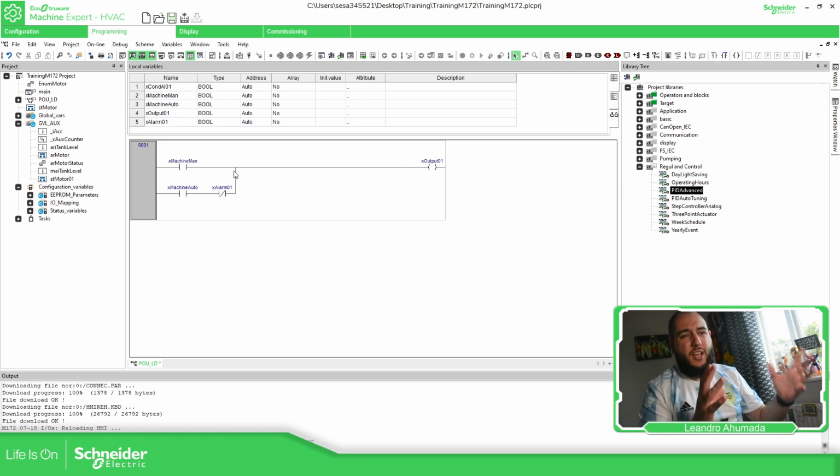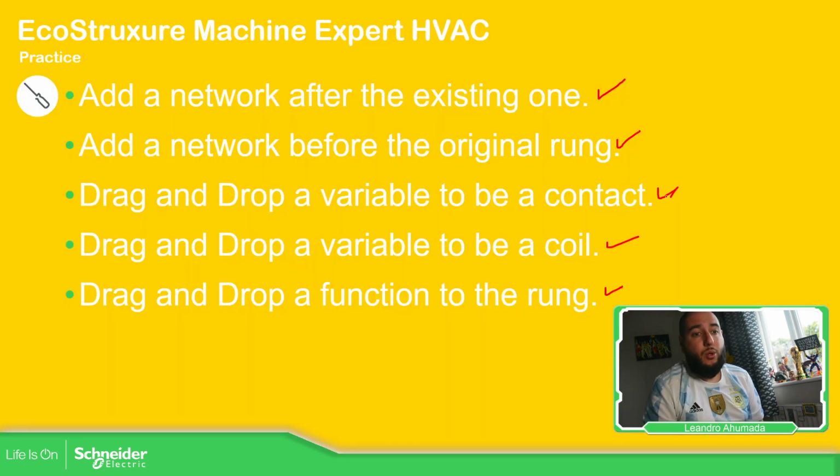So you can easily check, okay, I have the condition that came from the manual, I have the condition that came from the auto, or another one, and then you just see what happened with the output. So the ladder is easy, but probably it can generate more code if you need to make additional conditions. That's why I barely use the ladder, just to see inputs and outputs and maybe the conditions for the alarms. That's it, but it's up to you which one to use.